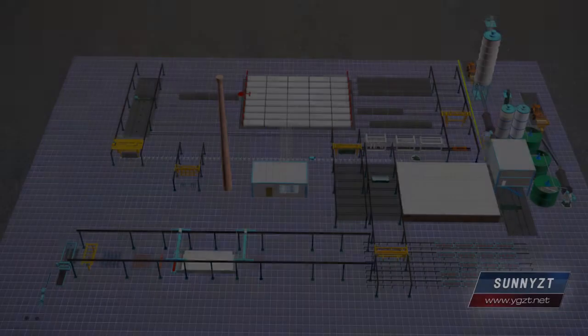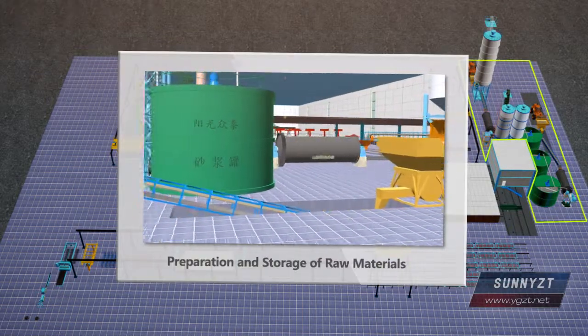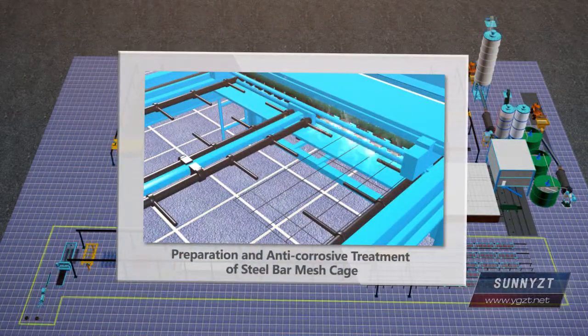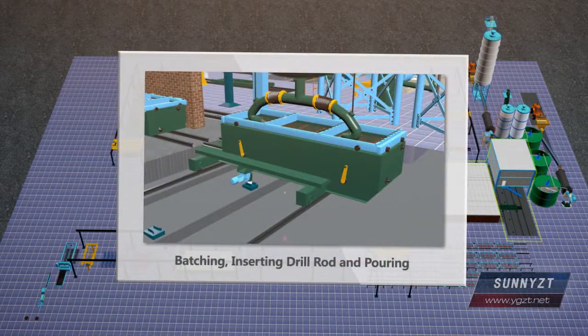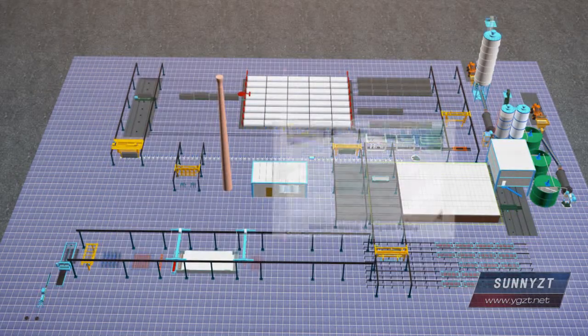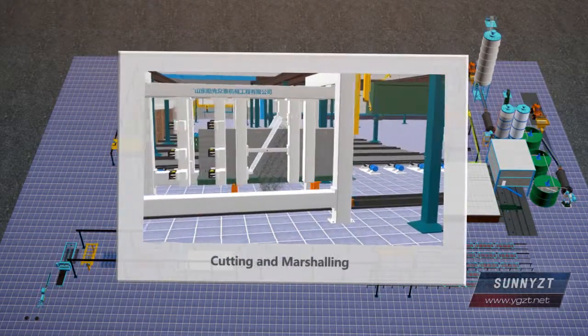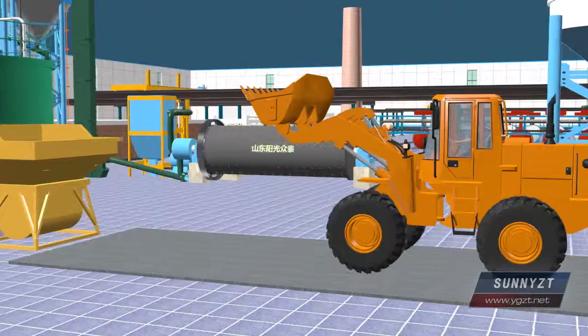Technological process of aerated concrete panel. The process of aerated concrete panel is divided into 6 parts: preparation and storage of raw materials, preparation and anti-corrosive treatment of steel bar mesh cage, batching, inserting drill rod and pouring, static hardening, curing and pulling, cutting and marshalling, autoclaving and finished product stockpiling.